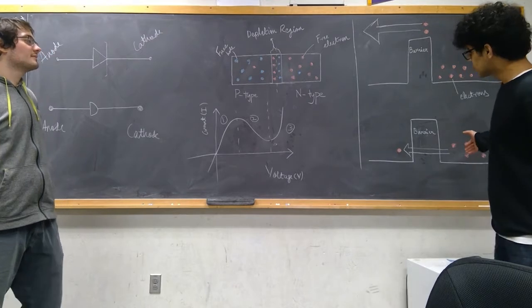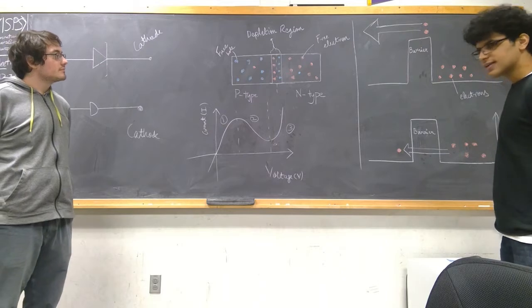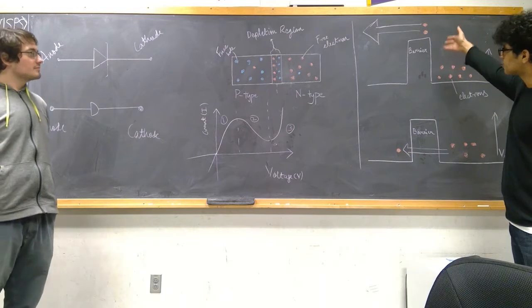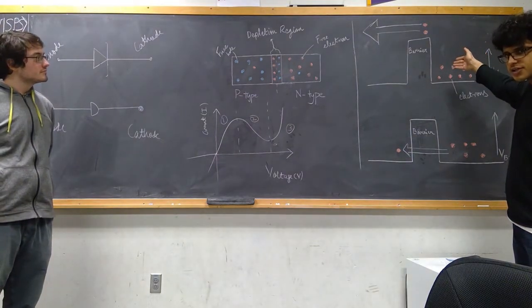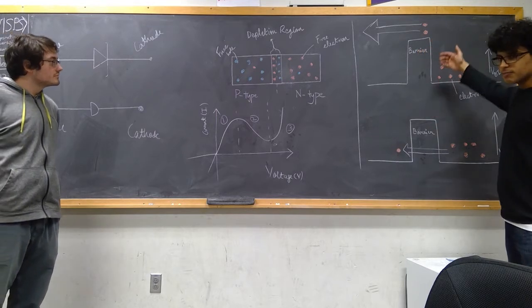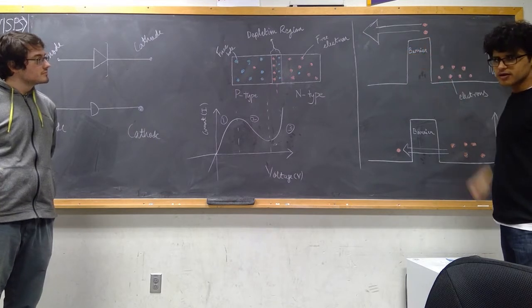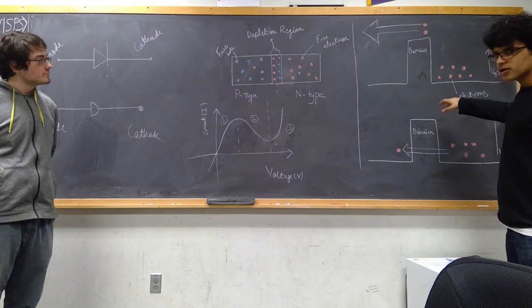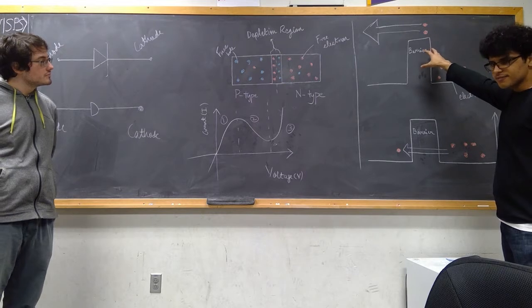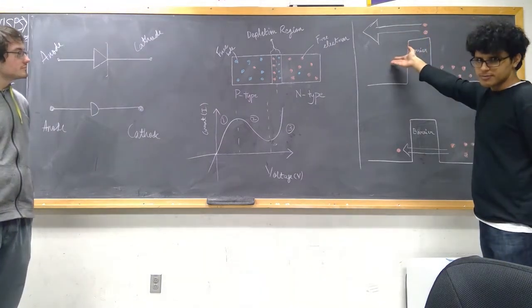These diagrams show us the energy diagrams for a normal PN diode and a tunneling diode. As Chase said, in a normal PN diode, electrons do not have the energy to pass over the barrier. Thus, the applied voltage has to surpass the built-in voltage in the depletion region so that either the barrier width is decreased and the electrons can flow easily, or one increases the energy of electrons while keeping the barrier height the same, so that electrons now have more energy than the barrier and can pass over the barrier.